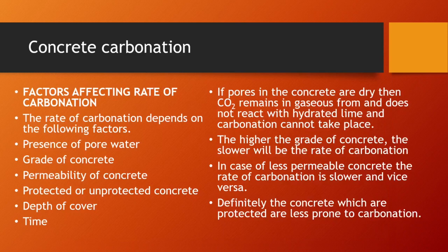So the carbonation itself depends on the following factors. The presence of pore water, so how much water is getting within the structure itself. It depends on the grade of the concrete and how permeable, how porous it is, how much water it allows to soak in. And how much unprotected concrete there is.